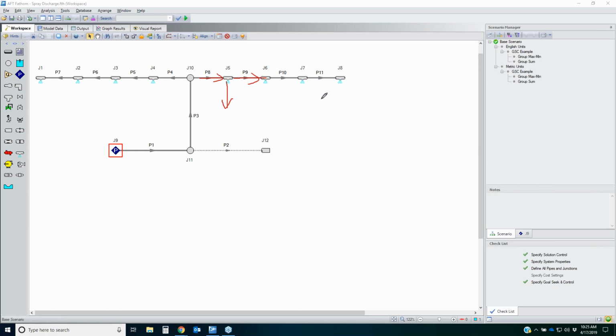So if we are trying to figure out what the flow rate through the junction is, what do you mean by the word through? Do you mean through the spray, through to the next pipe, or through some combination of them? The answer is there is no answer. It's ambiguous. So that's why for these spray nozzles that are in line with all of these pipes, you will see not applicable for their flow rates.